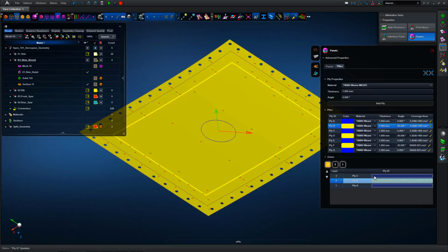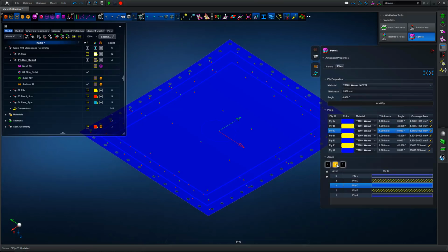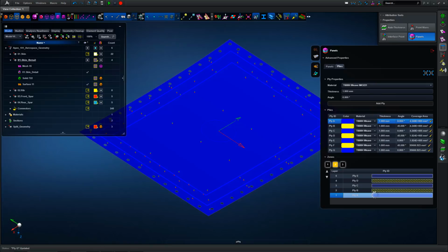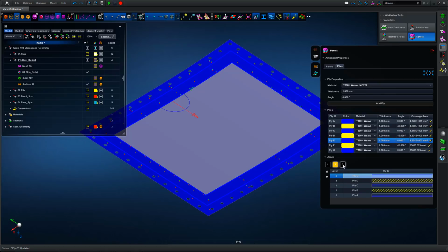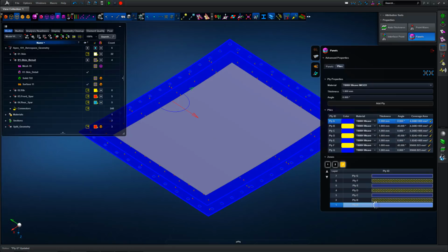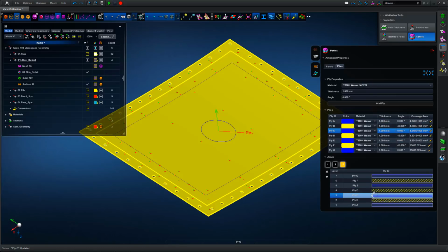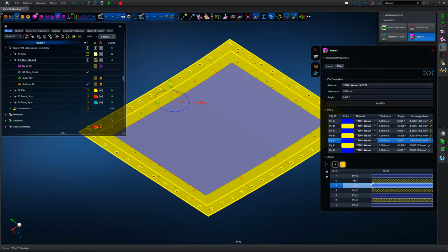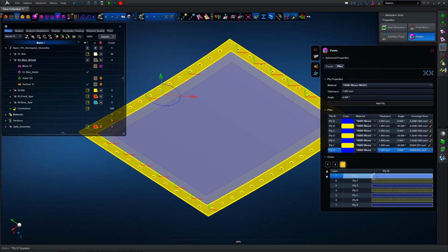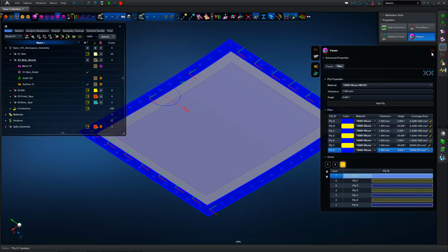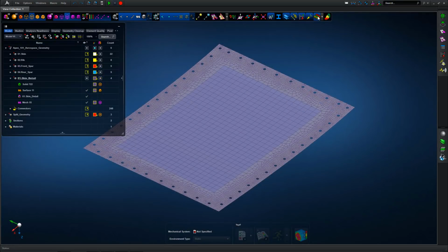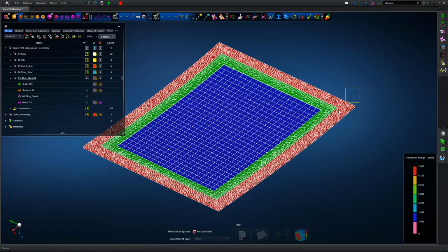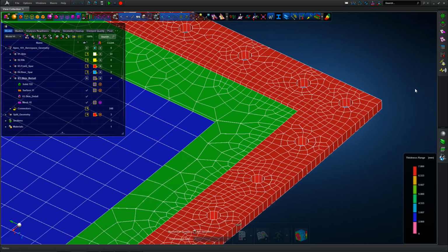And then working on a zone by zone basis, if we highlight the plies in the lower box as shown now, you can see the ply coverage, the colors of the plies, and again we've color coded them, and a graphic showing whether it's a 0 or 90 degree depending on our layup definition. So again, very easy to visualize what's going on with the plies at the given zone level and for the full laminate. So if we come out of the ply tool, or the panels tool I should say, and then double check the laminate thicknesses, again we can see the offset.